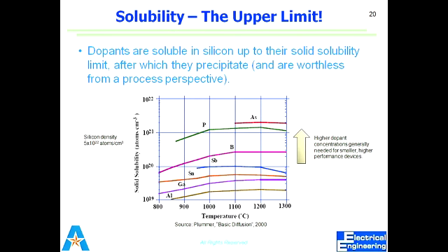As the graph shows, the higher the temperature, the higher the dopant. But at the same time, it also depends on what type of dopant you are using. Boron has a different solid solubility, phosphorus has even more solid solubility than that, and aluminium has very little solid solubility. So aluminium cannot cross this limit at 1300 degrees centigrade, but at this point boron has much higher. So the solid solubility of the dopant is an important factor.